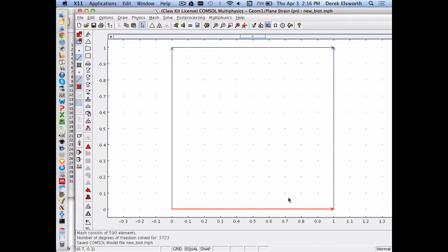We didn't talk about thermoelasticity, but thermoelasticity is actually directly analogous to poroelasticity. The body force in thermoelasticity is the thermal coefficient of expansion multiplied by the thermal gradient, dT dx. It's exactly analogous, but it's a one-way coupling. You apply a temperature, you get a deformation. You can't apply a deformation and get a temperature in the same way as you can in pore mechanics. There, you apply a deformation, you generate undrained fluid pressures, which then respond. So they're analogous, but the coupling is really only one way.